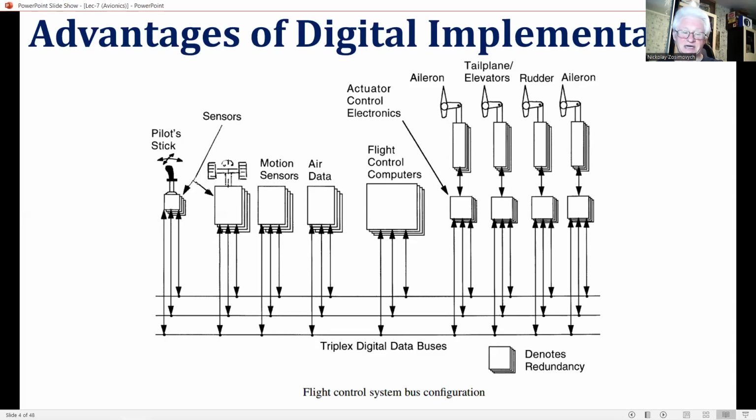The signal data are subsequently processed by a digital microprocessor in the flight control computer, which carries out the following tasks: voting, monitoring, and consolidation, control law implementation, reconfiguration in the event of failure, and built-in test and monitoring.